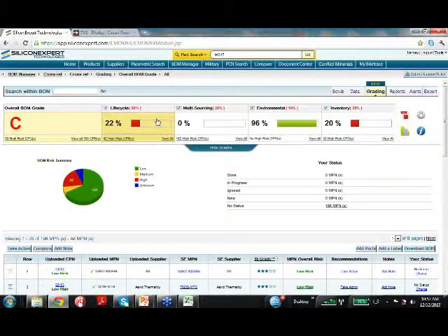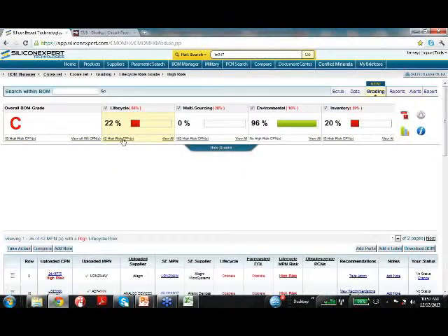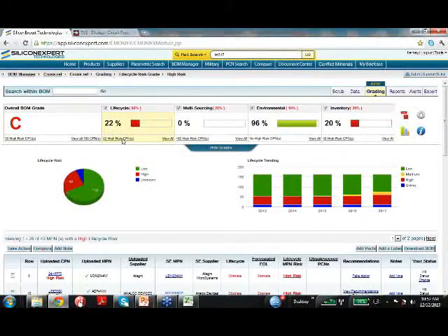For the most part, though, life cycle is the number one thing to look for, and so we weight that as 50% of the algorithm in this case. So you can quickly go to those 42 high-risk part numbers, which is what we were just looking at: the end-of-life parts, anything that was not recommended for new design, obsolete, or last time buy. You can download that BOM, and then upload that back in, and only focus on the high-risk parts. Rather than looking at the rest of the 100 or 200 parts in this BOM, we only need to really focus now on these parts that need to have cross-references found.